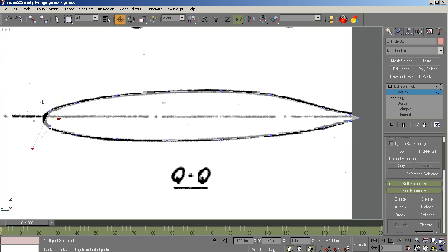Oops. That's what happens when you think you're fixing to select, but you grab a gizmo instead. One thing I usually do is I go with like an 18 on something like this. So you don't need that many to get an appearance of a round surface here. Let's pull this back and kind of split the distance.